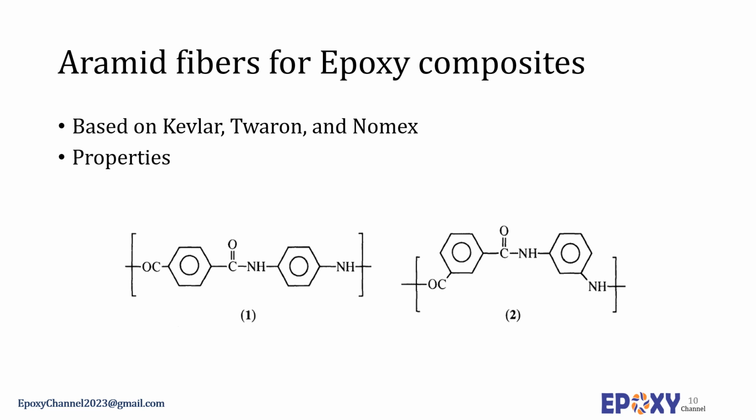These fibers have a poor fiber transverse strength and a tendency to fibrillate. Consequently, the fibers have poor compressive strength. Also, the adhesion between the fiber and the matrix, and between fiber crystalline planes, is poor in these composites. The fiber-resin adhesion can be improved by using plasma-type surface treatments. Also, it is possible to increase fiber integrity by gamma irradiation cross-linking, but commercially treated fibers are not generally available.